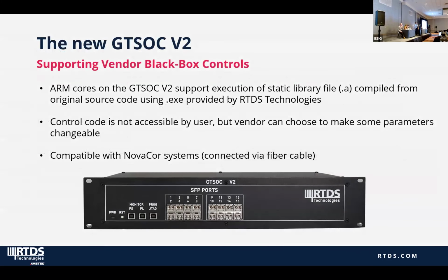Probably the most important one today, especially with the discussions that we're having here about looking at inverter-based systems and their penetration into the grid, is to use this GT SOC box for vendor black box modeling. So vendors are creating black box models that operate and run on this actual platform, and that's connected into the RTDS simulator. So you have something that's very analogous to an external controller. The controller is implemented on the GT SOC, running on the ARM cores, and then that system is connected into the real-time simulation that's running on the RTDS hardware.